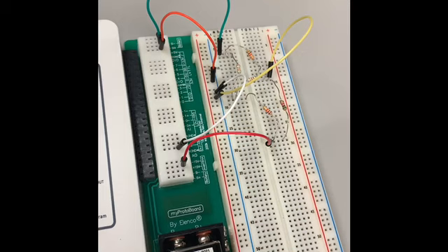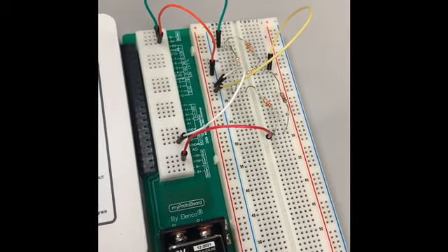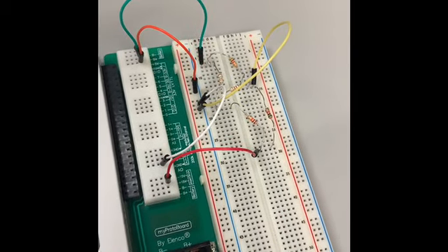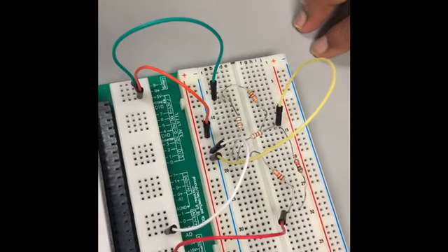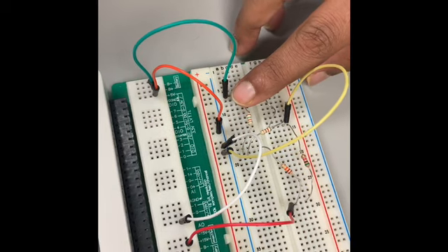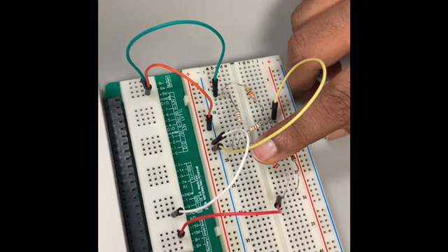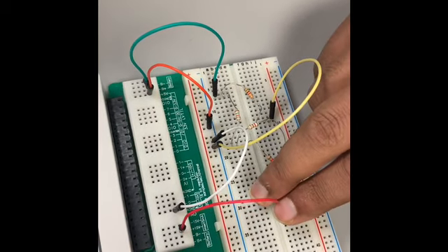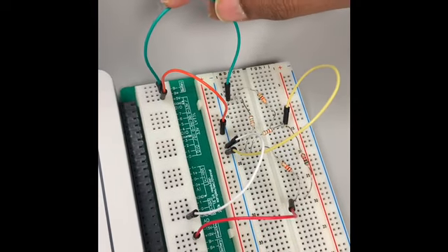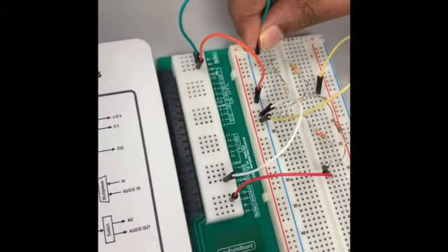All right, so this is the first part of the procedure, and we have our MyDAC hooked up to our computer using the multimeter. We've already constructed the circuit shown in figure 1, and we'll just show you what each one is before we start. So first we have our 5.1 kilo ohm resistor, next our 1.5 kilo ohm, 820 ohm, 12 kilo ohm, and 5.1 ohm. And then the red wire is our 15 volt supply, and the green wire is our 5 volt supply. We'll start by measuring the current for this, and to do that, it's in series.